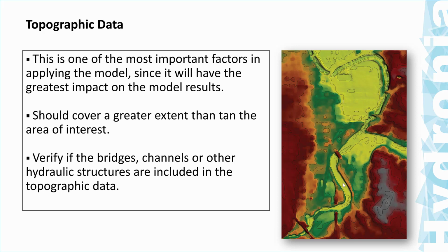Now, we will cover this, but you need to be aware that sometimes the digital elevation models that are generated by some techniques like LiDAR and even satellite include artifacts that contain part of the man-made structures like bridges, for instance.